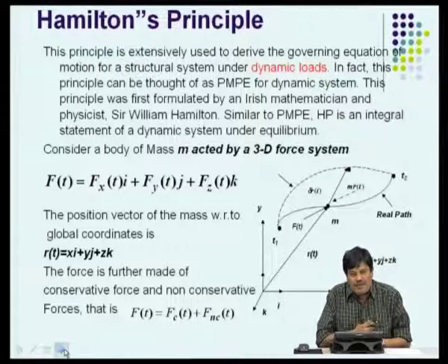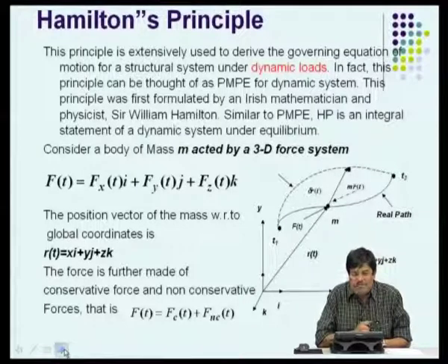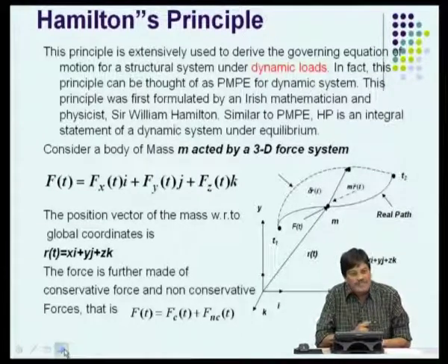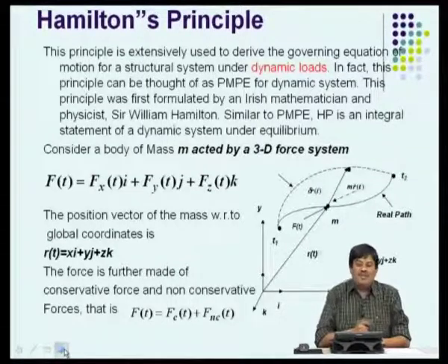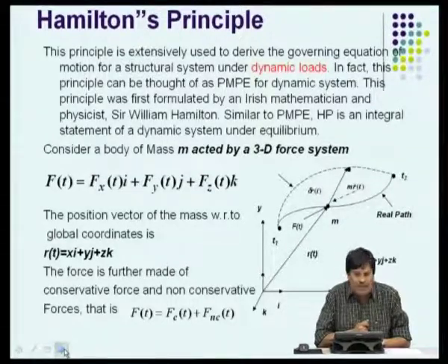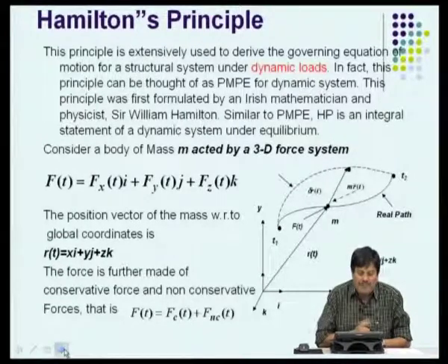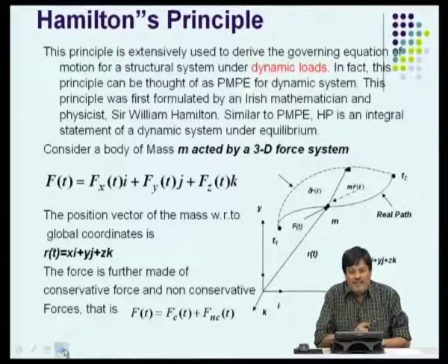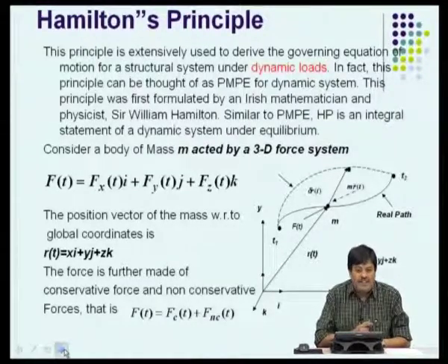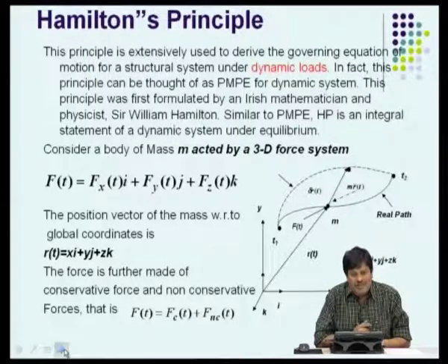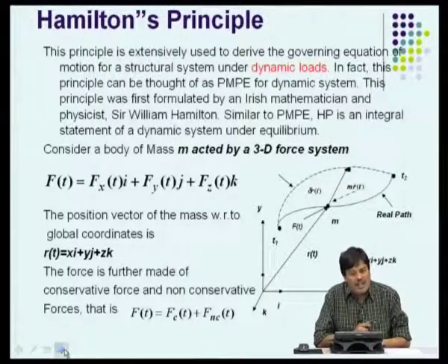The next important principle that we want to discuss here is Hamilton's principle. What is this Hamilton's principle? It is nothing but the principle of minimum potential energy under dynamic systems. So, the principle of potential energy we derived was based on the assumption that the loads are gradually applied. When the loads are suddenly applied and over a short duration, the dynamic effects come into the picture. To handle this, it was way back in 1800s that Sir William Hamilton propounded this theorem, which has a very fine theoretical basis. We will try to derive this equation by using the principle of minimum potential energy and see how we can do this.